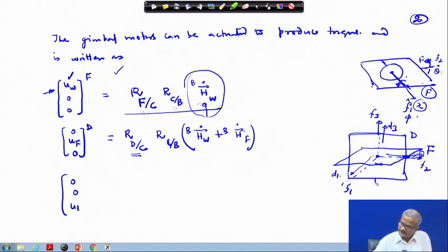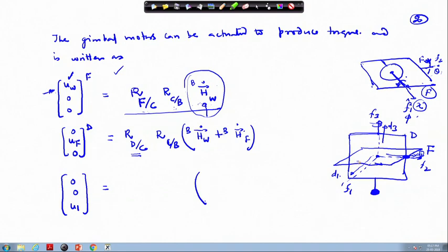So, this frame also is being actuated. One motor is attached at this point, so the outer frame will be rotating. It will accelerate. So, this we need to convert also. So, your wheel angular momentum changes because of the rotation of the external motor also. So, that also we have to take into account. So, for that we write